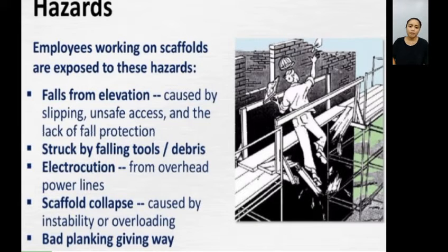Employees working on scaffolds are exposed to these hazards: fall protection, falls from elevation caused by slipping and unsafe access and lack of fall protection, struck by falling tools or debris. Are there requirements for work on a platform cluttered with debris?